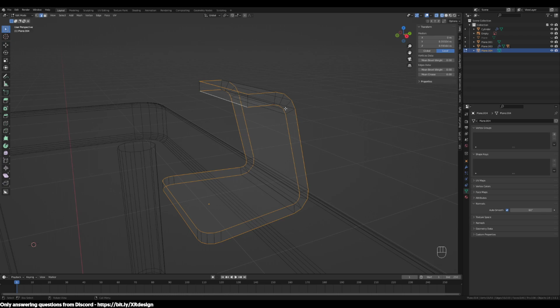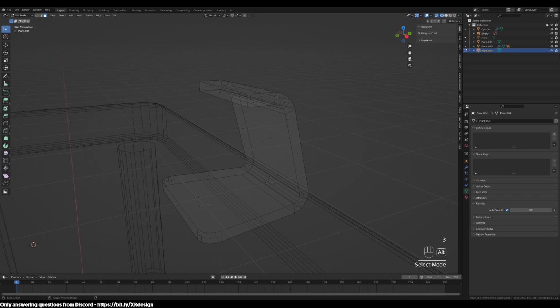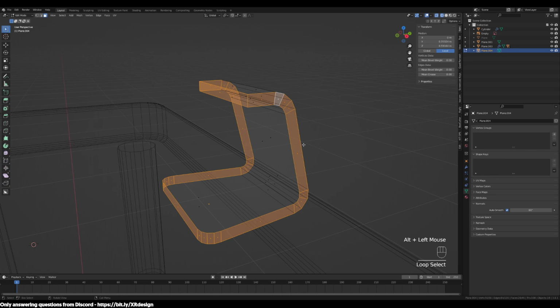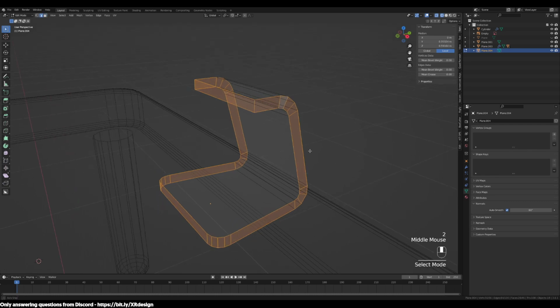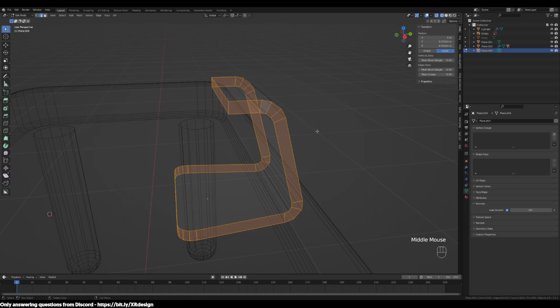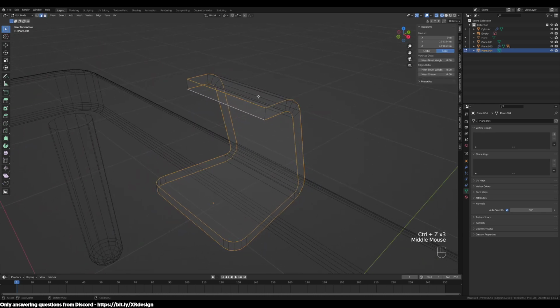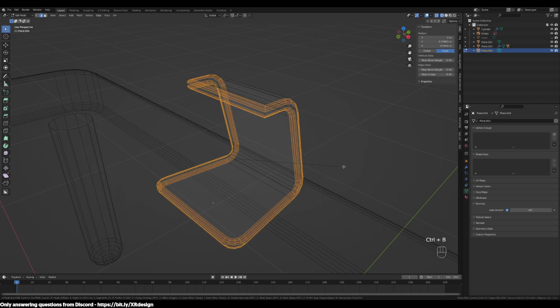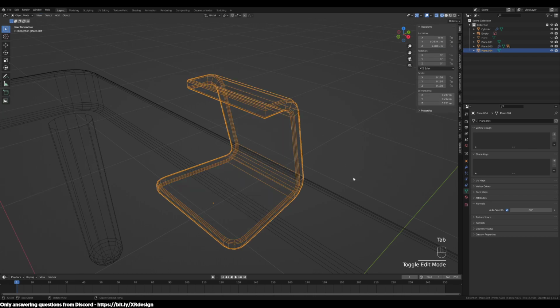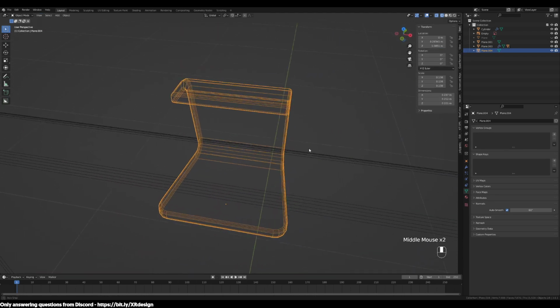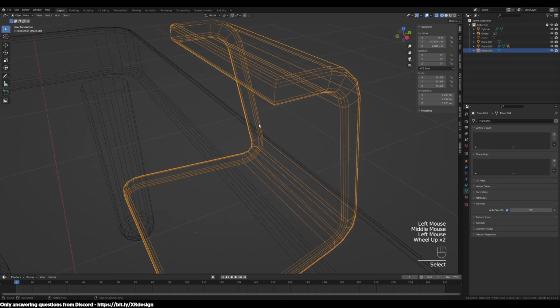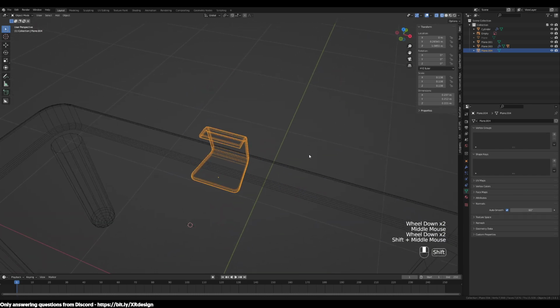So once you've selected everything, it should look like this. And I just realized that I could have just gone to face select and done this. But actually that wouldn't work because we're selecting the middle edges here. So what I was doing was right. Just go to edge select, select the outside, like so. And then Control B. Let's round that a little bit. And there you have it. That's the stand. I'm not going to curve these two edges because we're not going to be seeing that. It's going to be behind the display.